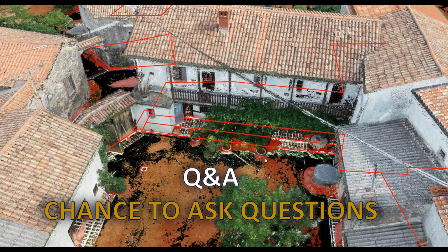So this is not like when we have, for example, roofs of the buildings projected onto the ground and they get distorted. If we use traditional orthophoto, here this is not the case. So the walls will not be distorted because if we are draping them onto digital terrain model, we should always drape them on the digital terrain model to get the best result. Okay.